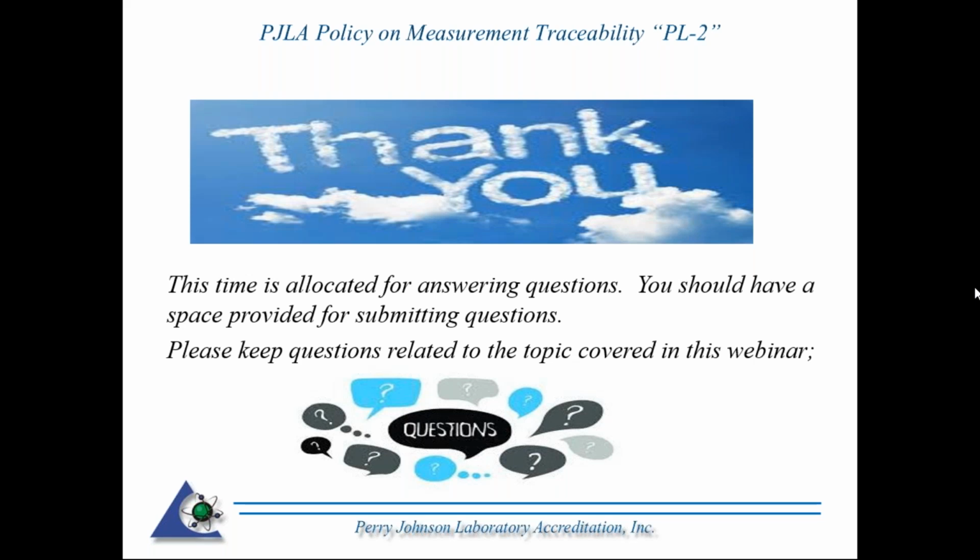Typically, as I mentioned earlier, when you get that report from the NMI, in this case the German NMI, it should have the measurement uncertainty on there. Typically, when it comes off a report from your provider, that's considered a normal distribution, and you need to look at the K factor, in other words, the confidence interval. If you're getting it off the report, I can tell you 99.5% of the time, the K factor should be 2.